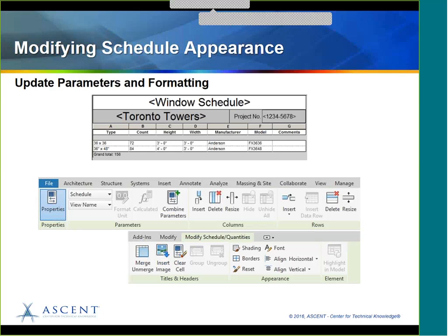Someone just wanted to make sure, is what you're covering today, is Revit LT 2018 included? Oh, I always forget what's in and what's not in LT. So some of these things are. Yeah, I think I've looked it up. LT doesn't do embedded schedules. It doesn't do panel schedules, duct and pipe pressure loss reports. Okay, thanks for checking that. And it might be this combined parameters may not be, I faintly remember that, but most everything that we're doing, I think it does. Okay. Yeah, there's someone who just had checked on that.